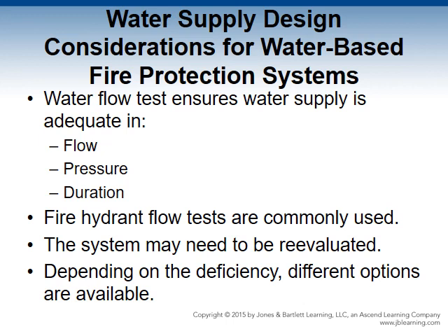For the purpose of designing a system for a new structure, fire hydrant flow tests are the most commonly used. These tests require special equipment, information concerning the distribution system, and knowledge of the testing procedures. When upgrading existing water-based fire protection systems in a structure containing a fire pump, it is more common to use a fire pump performance test or the 2-inch drain test.